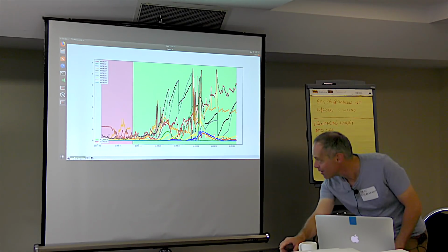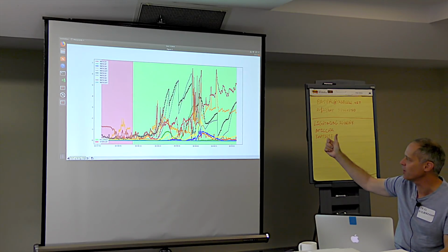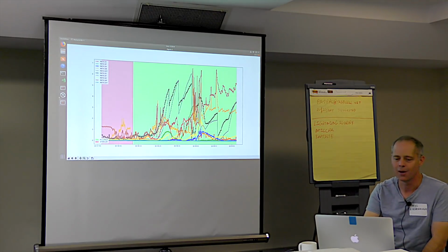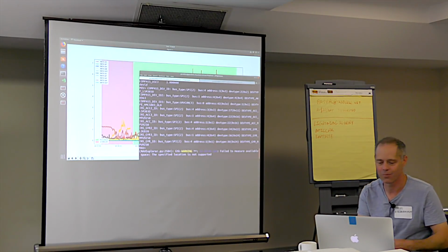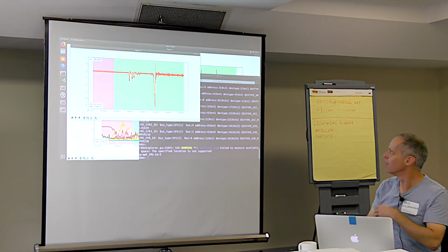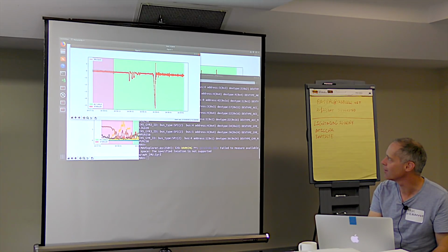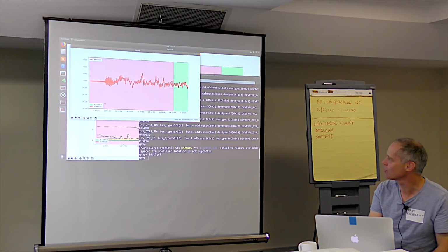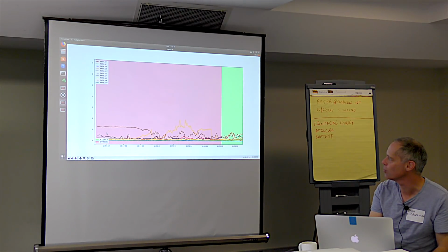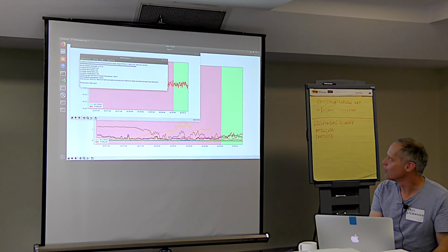Now, what does the user do to go between a failure on the magnetometer on EKF2, on the second EKF, to a failure on the first EKF? The answer is they just did a yaw rotation. No, they didn't do a yaw rotation. So now we've got a magnetometer that's failed and come good, another one that's been good and failed, and the user hasn't rotated in yaw. Oh, there we go. So how do we resolve that?